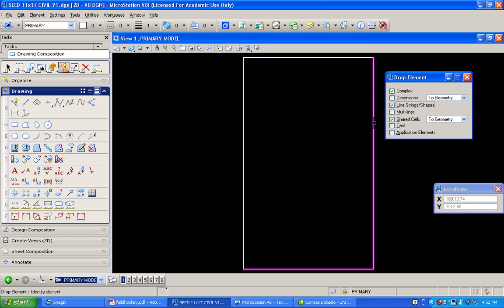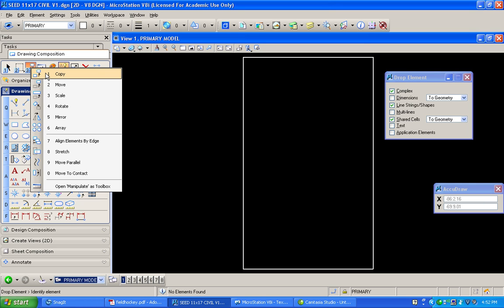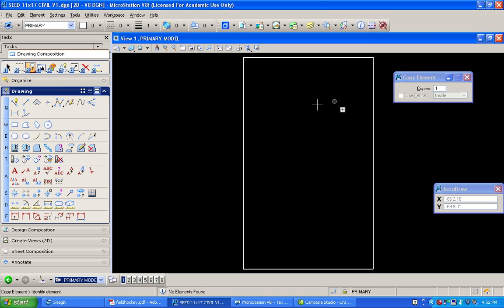The other thing it said in the description was that all of these lines are 3 inches wide. So we're going to make a copy of these lines. We can just say copy, or you could use the move parallel tool. But we're going to copy these lines. Just left click on this line, bring it to the left, key in :3. And you can actually use the semicolon. You see now what we've got is a 3-inch thick line.